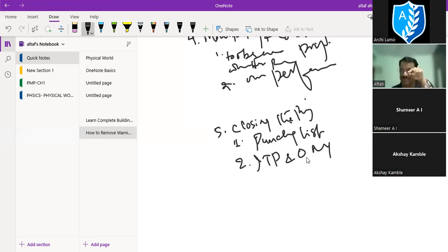So in the closing stage, a snag list or punch list has to be prepared and the items cleared and rectified immediately. An ITP, inspection, testing and project plan, is to be prepared. And as per that, the operation manual: if there is a BIM application, or some special computer system, or even the substation part, how it is connected, how the building will be managed, operated and maintained, that operation and maintenance manual is also